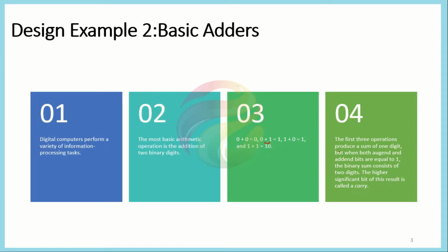The next process is the same: if the numbers have more than a single bit, say two binary numbers each representing a 3-bit number, we first add the first column, and then see if any carry is generated. We transfer that carry to the next column, perform the addition accordingly, and then move to the next column. In the same way, we will try to design a hardware that could implement the basic addition process of given binary numbers.